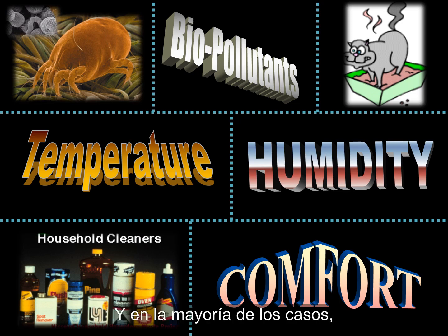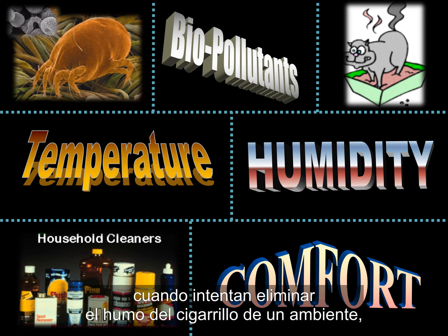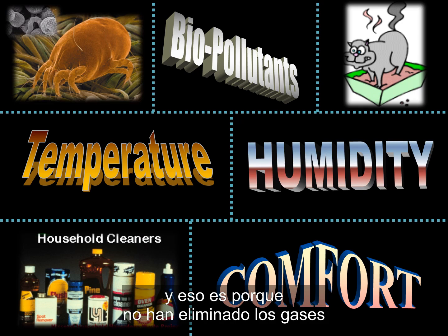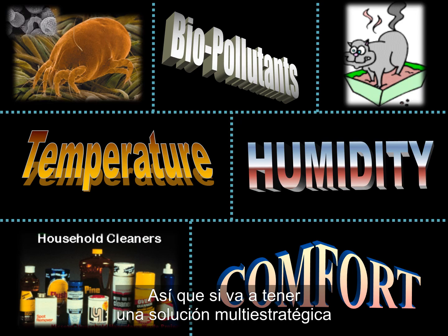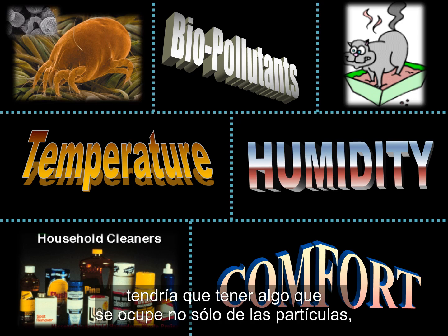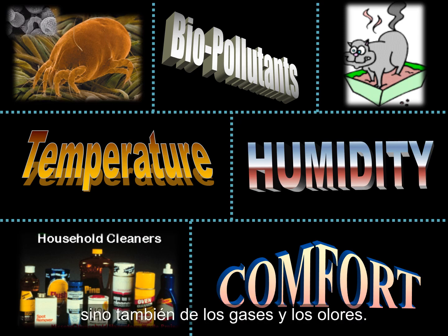And in most cases, when they try to take cigarette smoke out of an environment, like in a bar or a restaurant, they use a filter, and so they're successful at taking the particles out, but it still smells like an ashtray. And that's because they haven't removed the gases and the odors that remain. So if you were going to have a multi-strategic solution to secondhand smoke, you'd have to have something that would deal with not only the particulates, but also deal with the gases and with the odors.